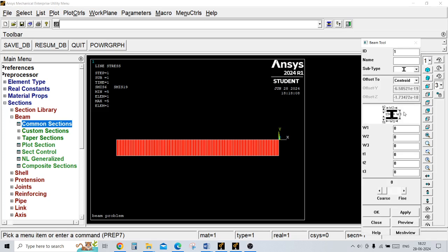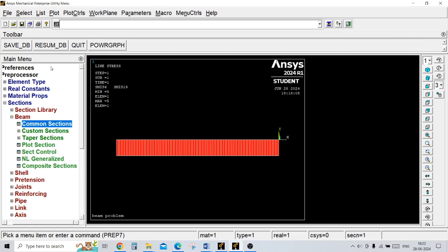On selecting this, we give the parameters described in the figure: width 1, width 2, width 3 and thickness 1, thickness 2, thickness 3. On giving these values, it automatically calculates the moment of inertia, and the combination of E and I, and uses them in the formulas to display the required results.